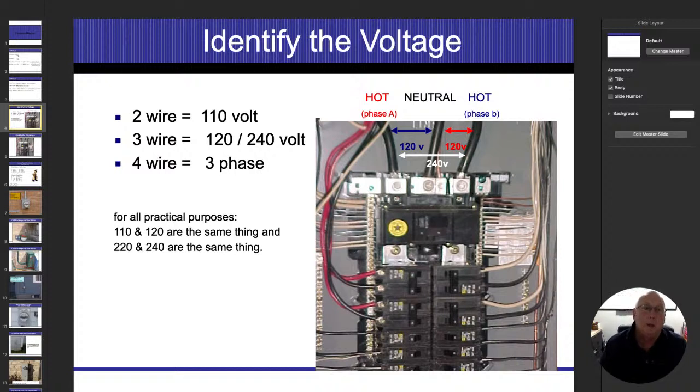Now I really don't care if you say 110, 115, 120, none of that really means anything to me. Because again, we're not going to get the exact voltage that comes in there. What I do care about is that when we get to a single phase with 2 energized conductors, we use the proper terms. So if I have 3 wires coming in, the first wire is going to be the neutral wire again. Then I'm going to have 2 energized conductors. Those 2 energized conductors make a combination system, and we're going to refer to it as either 110/220, 115/230, 120/240, whatever it is. Whatever you use on that first number, all I'm asking is that you double it. It's going to discredit you real quick if you try to say that it's 110/240 or something like that. So just using the right terms is always best.